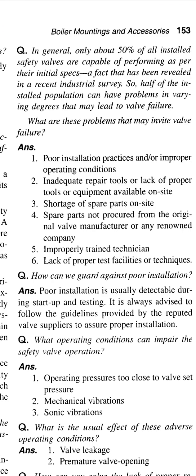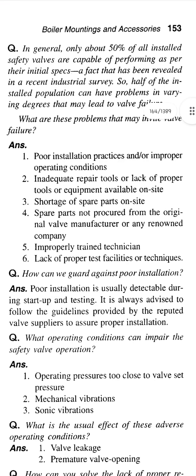Answer: poor installation practice and/or improper operating conditions, inadequate repair tools or lack of proper tools or equipment available on site, shortage of spare parts on site, spare parts not procured from the original valve manufacturer or any renowned company, improperly trained technicians, lack of proper test facilities or techniques.